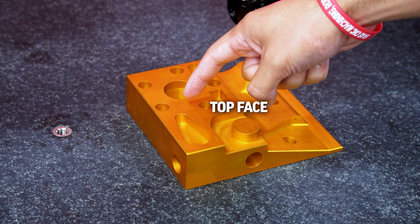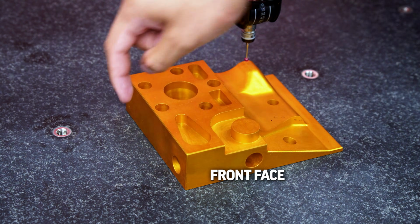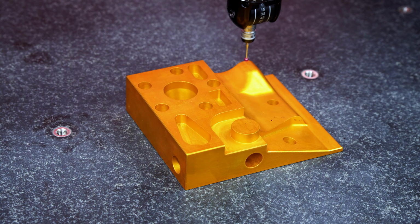For this demonstration, I'll use the 3-2-1 alignment method to define the part coordinate system and to constrain all 6 degrees of freedom, 3 translational and 3 rotational. I'll measure 3 planes for this specific CAD model: the top face, the front face, and the left face. These planes will establish a repeatable datum structure for accurate part alignment.